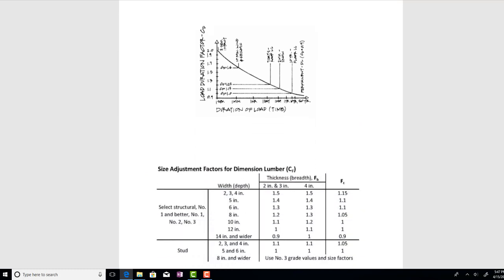This particular diagram showed up with our timber properties. Remember that with timber, if the load is on there for a short duration of time, then the timber actually has more carrying capacity, and we ended up increasing by a factor of 2. This is our load duration factor, where our default value is the 10-year load, and it's got a duration factor of 1.0. So if we've got a load on there longer than 10 years, a permanent load we call that, then you multiply by a value of 0.9, which reduces it by 10%.